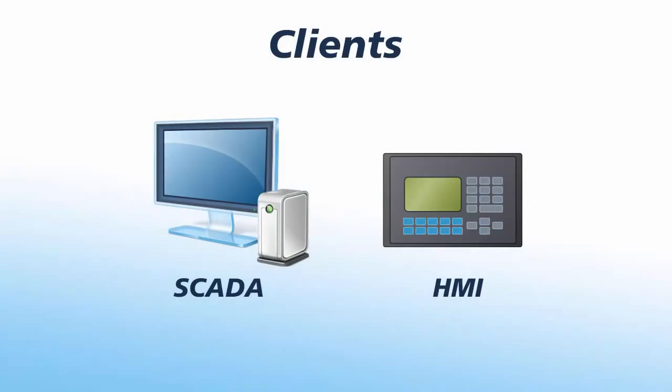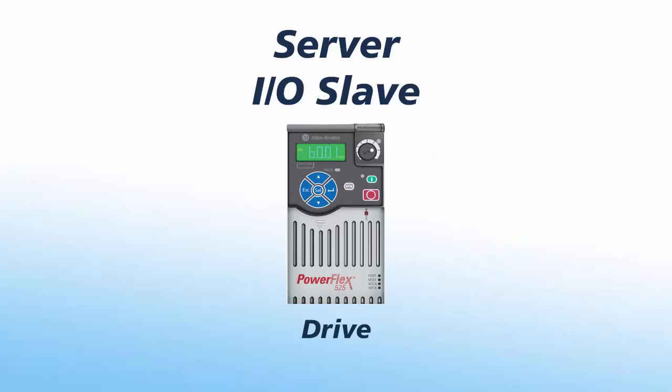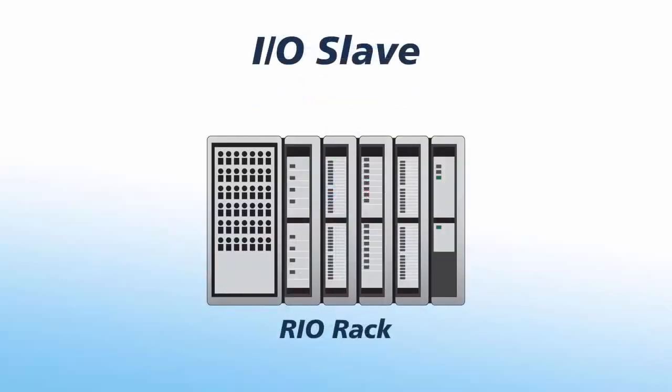SCADA hosts or HMI terminals, on the other hand, are almost always configured as a client. Other devices such as drives can act as a server or as an I/O message slave, whereas remote I/O racks primarily act as I/O messaging slaves but can act as servers depending on the protocol.